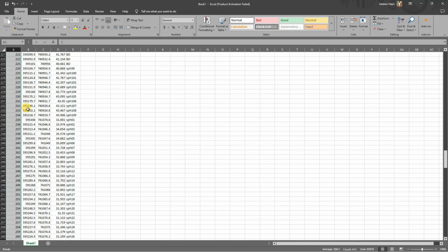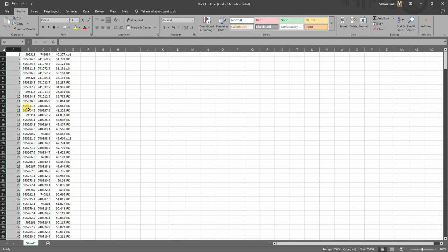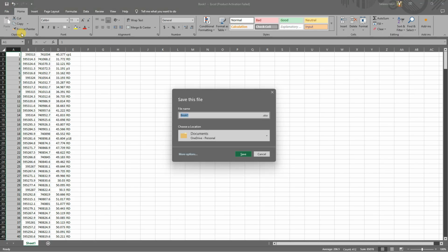So now after that, you can save your work from here as .csv, which the import tool in AutoCAD Civil 3D will understand and recognize. Or you can copy this whole text again and take it back to the notepad, then paste it, then add the delimiter, then save and import. But here I'm going to be saving this document as CSV and then importing back into AutoCAD. So to do that, we click on save, or you do Ctrl S as we know.